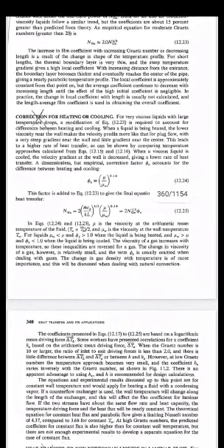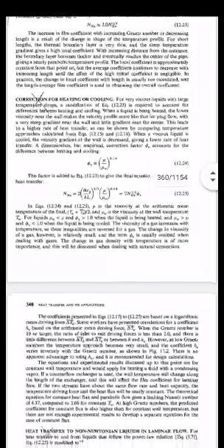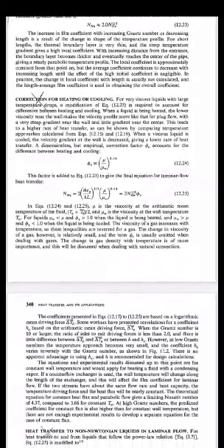So this correction factor, mu upon mu w raised to 0.14, is added in the final equation for laminar flow heat transfer. Here again, the Nusselt number can be rewritten as 2 times (m dot cp upon kL) raised to 1 upon 3 into (mu upon mu w) raised to 0.14, which can be said as 2 times Graetz number raised to 1 upon 3 and phi e.